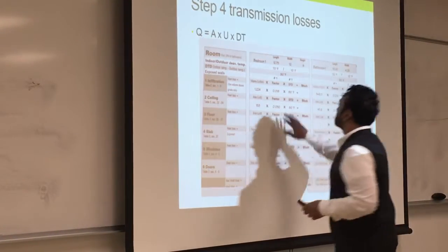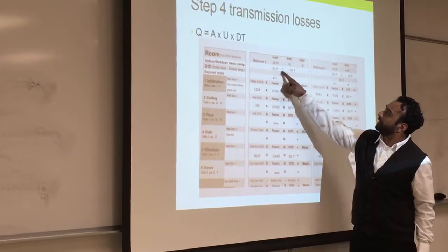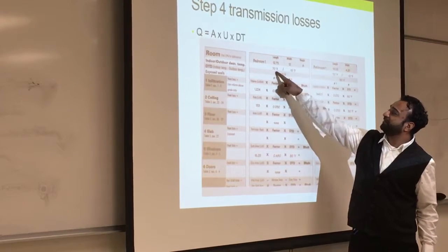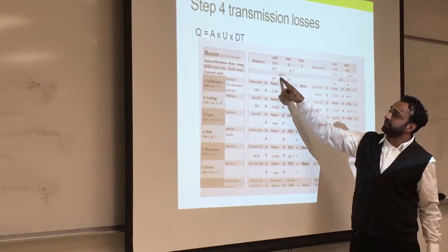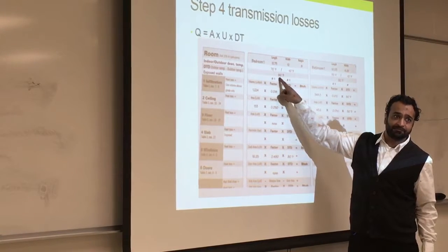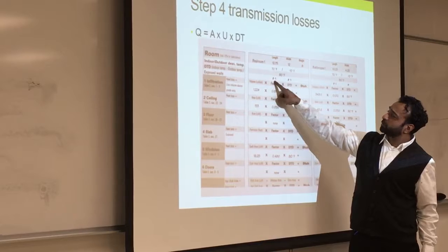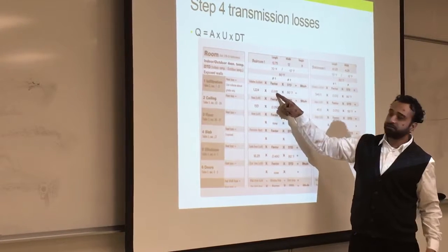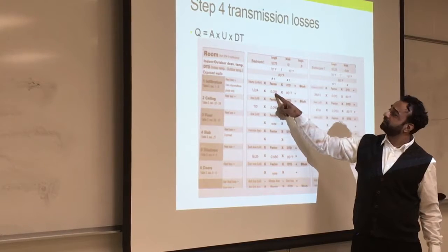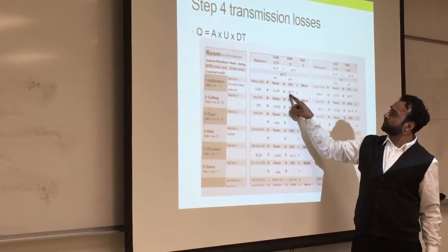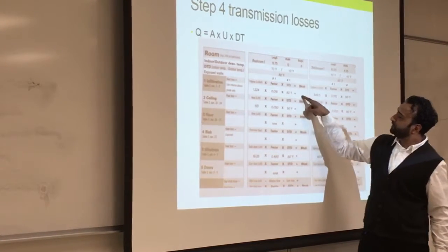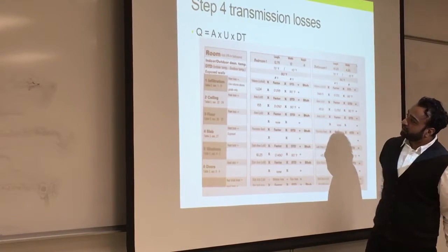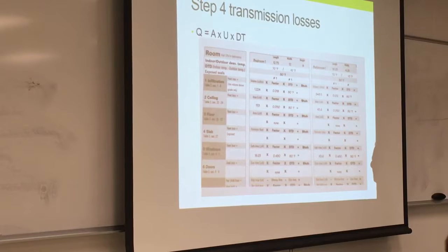So, that's my factor, that's my volume. This is an example of a room. I put the length, width, height, I have the inside and outside temperature. Delta T is here, it is 80. Exposed wall is 1. Volume, you multiply these 3. Factor, I got it from the table. DTD, BTU will come in here. And the rest are all going to be transmission.